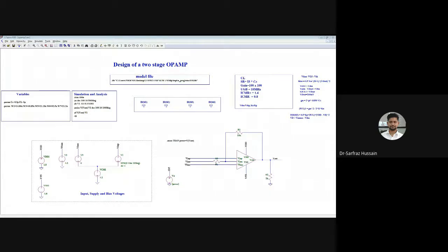And if you want to check the worst case analysis, you can use the dot function. By using that dot function SPICE directive, you can build up some more powerful functions. You can even make them for PVT analysis, and if you want to vary temperature, or any other parameter, temperature you can also vary here.